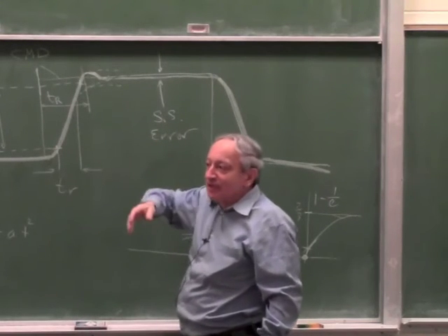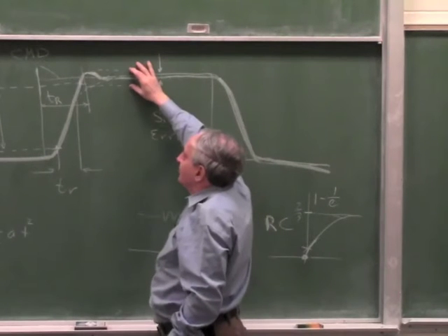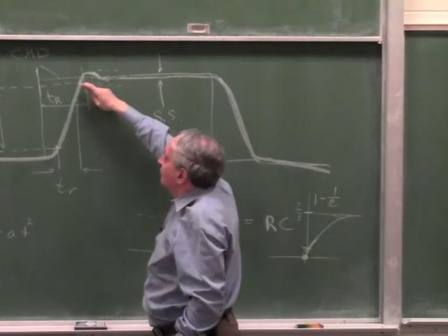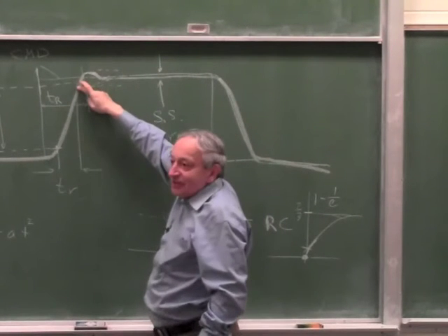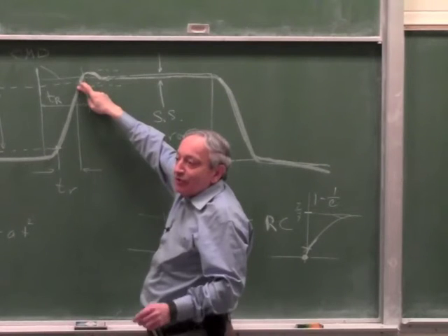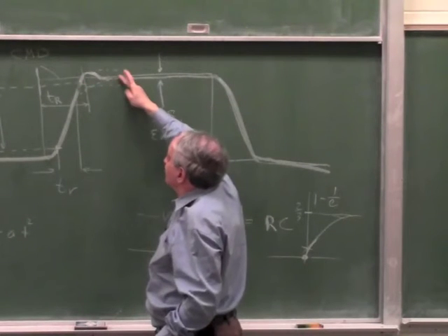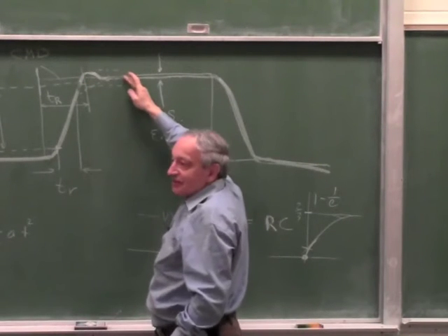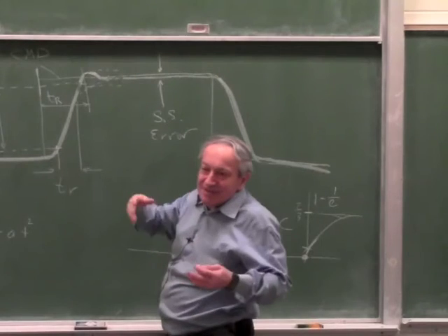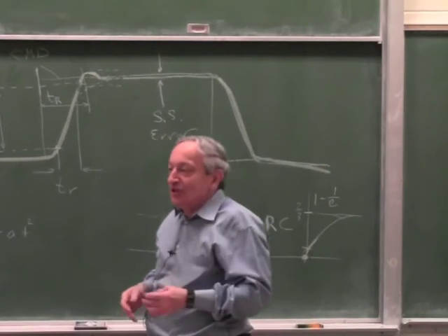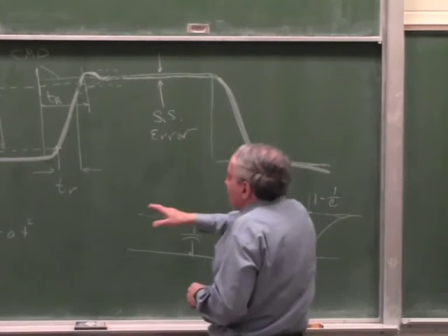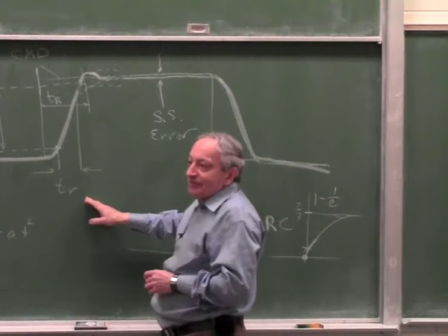If the servo is not critical, if it has to be within 10%, your response time will be up to this point. If the servo is a servo to 0.1%, your response time will be up to this point, because it's still settling. So the response time is a vague term depending on your need of the servo. The rise time is a more clearly defined term.